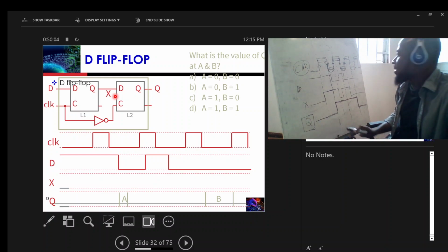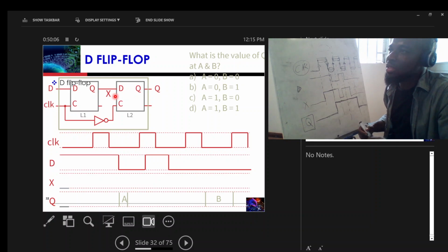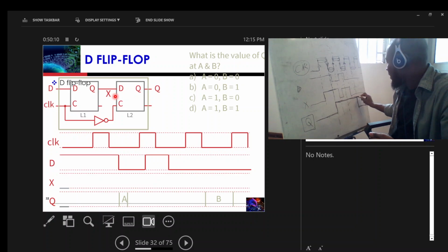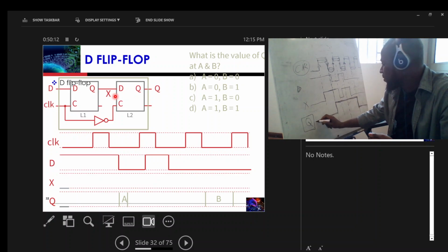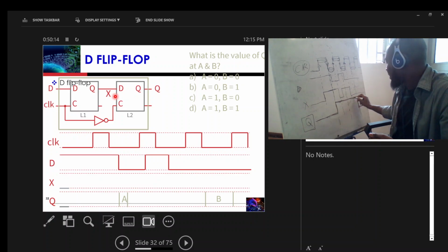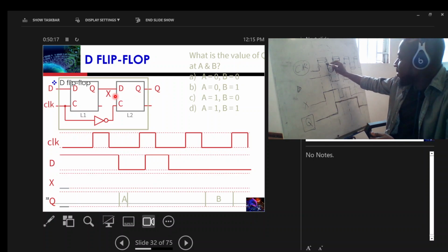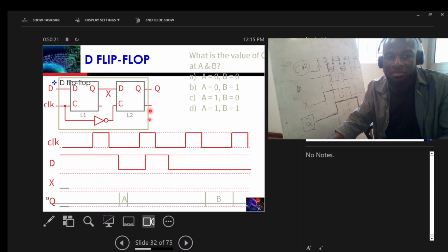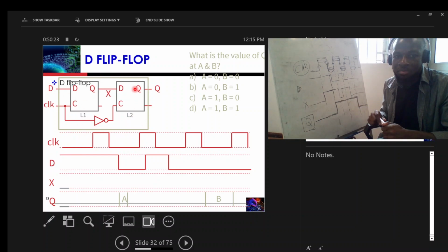So this is the D flip-flop, and then we say that the D flip-flop is edge triggered, right? As you can see, the value was made available, or the value was sampled only at the negative edges of the clock, right here, based on the configuration, based on this flip-flop design. So you have to look at the design of the flip-flop.